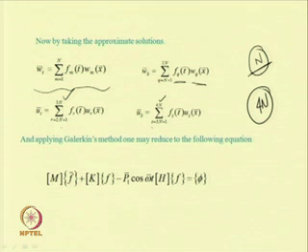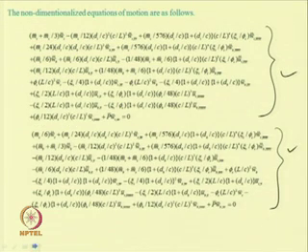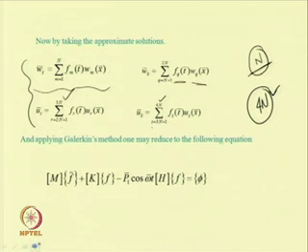state vectors present in this equation of motion. So, we can have 4 n state vectors. Now, substituting these equations W t bar, W b bar, U t bar and U b bar, these equations all with multi modes, by substituting these equations in our previous equations, so these two and these two, these 4 equations, now substituting these in this equation and applying Galerkin method, we can write this equation in this form.